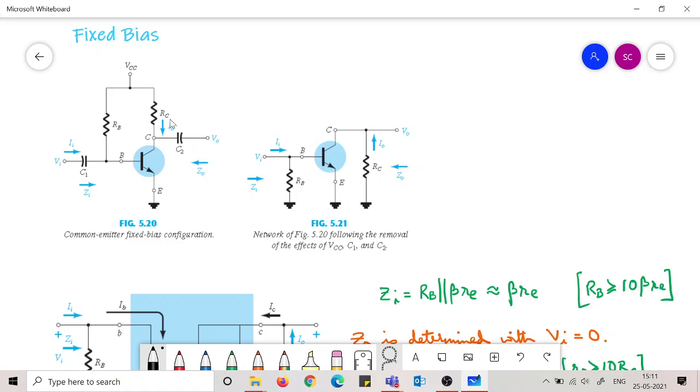Okay. So now you also note the direction of the currents. We have kept the direction of the currents as in the original circuit. So for I0, RC is assumed to be, you can say, as if a load resistance, but it is not an outside load. This is a load of the network. So the output current, being the IC or I0, has to flow in this branch, and we have connected a resistance here. So it behaves as a load resistance to this circuit.